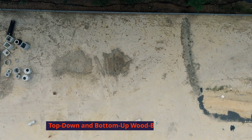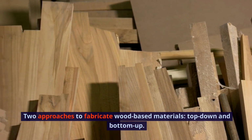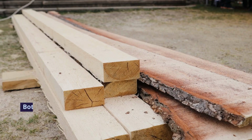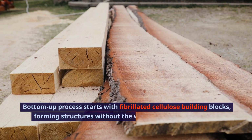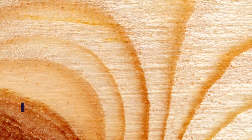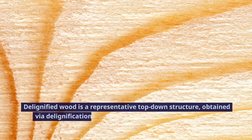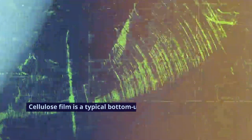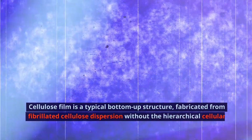Top-down and bottom-up wood-based structures. There are 2 approaches to fabricate wood-based materials: top-down and bottom-up. Top-down process preserves the hierarchical cellular microstructure of raw wood. Bottom-up process starts with fibrillated cellulose building blocks, forming structures without the wood's hierarchical cellular microstructure. Examples of top-down and bottom-up structures. Delignified wood is a representative top-down structure, obtained via delignification process, preserving hierarchical cellular structure. Cellulose film is a typical bottom-up structure, fabricated from fibrillated cellulose dispersion without the hierarchical cellular wood structure.